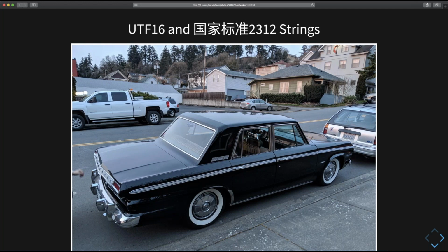So sometimes when you're looking through a firmware image for a device that has a screen display in Chinese, but not in English, and you run strings on it, and you look for Unicode strings, and you find none of it, you will still find GB2312 strings if you try that. And you can then run them through Google Translate and use those strings to understand the meaning of the code involved.